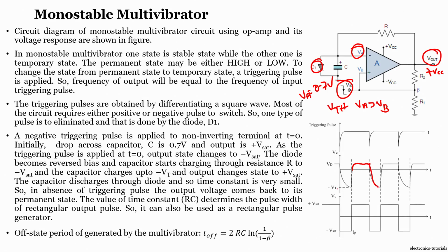Till our threshold value, isn't it? Why not to minus VCC? The reason is that, even from the astable multivibrator or the Schmitt trigger, when the input voltage is smaller than our negative threshold value, it goes to plus VCC again, right. So that means it will discharge only till minus VCC, right. So that decides